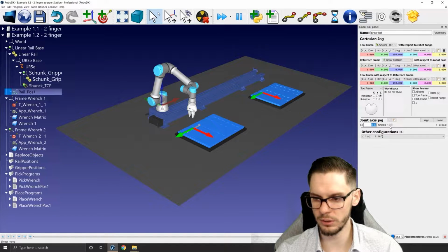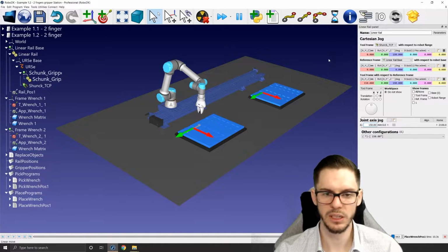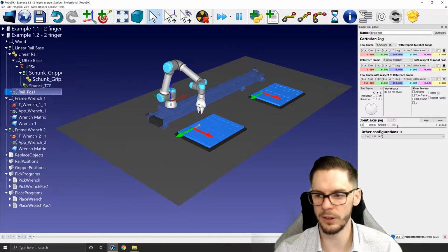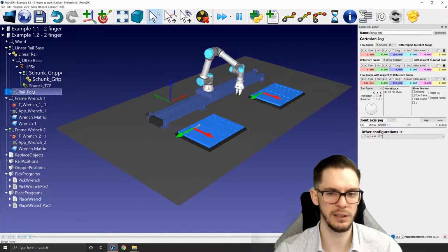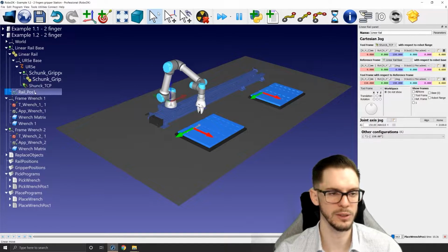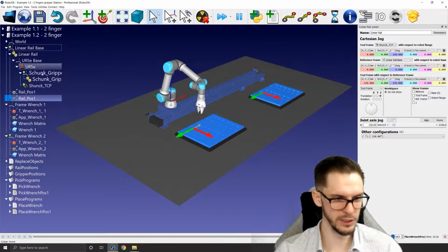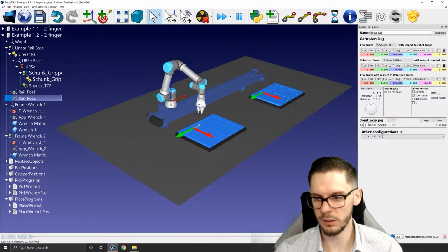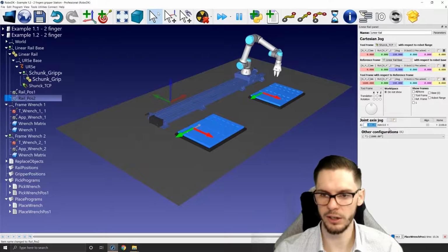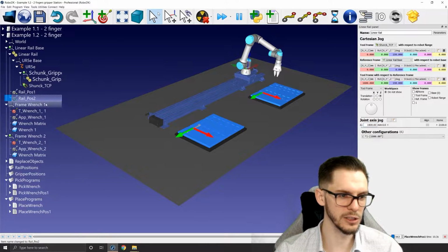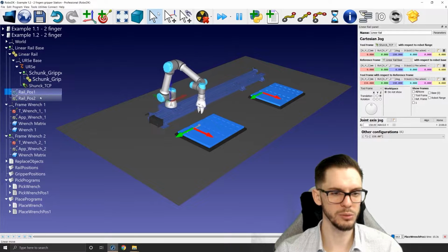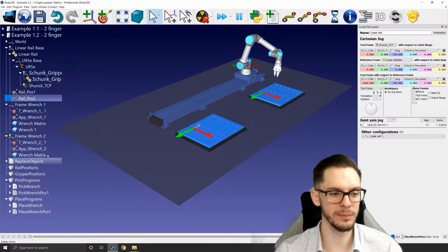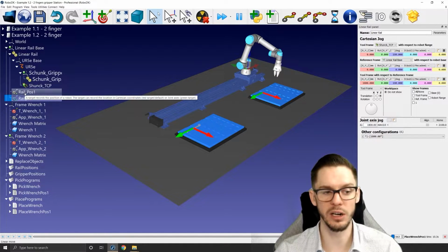And now I need to go to 150 here, and I'll right click and click teach current position. So now no matter where I place the linear rail, if I click here, it will be back at 150 millimeters. I can Control C and then Control V this one, F2, and then rename it. I'll bring that to 1800 and then right click teach current position, position 1, and then position 2. Perfect.